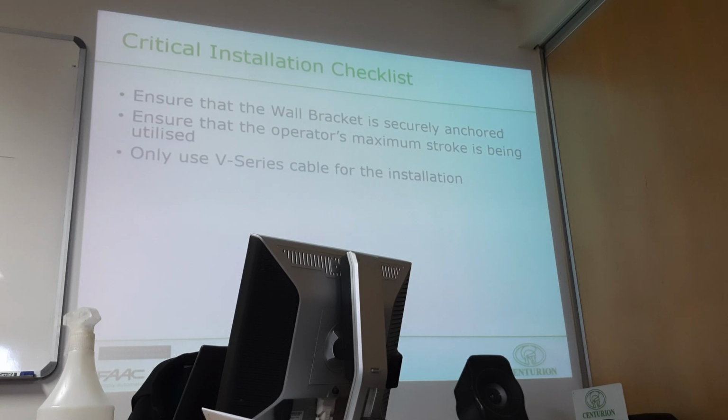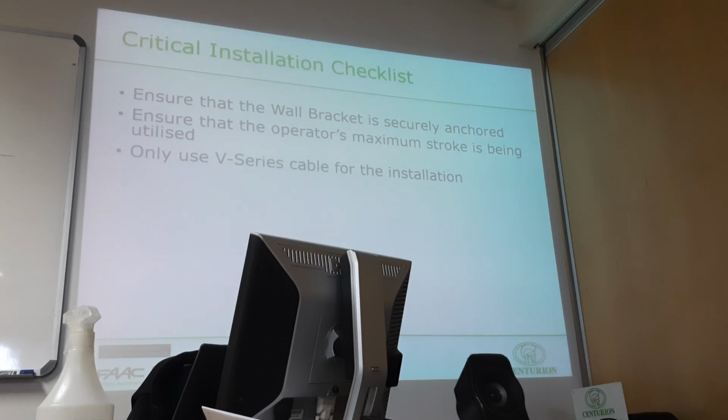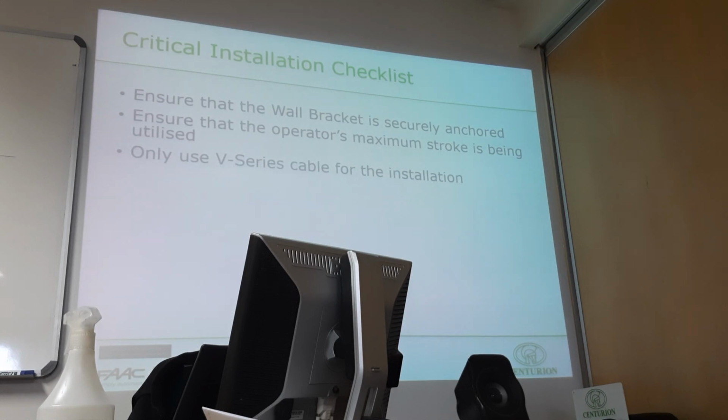Someone takes trailer cable, which is like a Cat 5 but it's got 7 cables in it, which is not shielded. So it's a nice thick cable, but it doesn't protect against any outside interference from the world into this controller. Then you have the DOS issues. Then it doesn't work, it's jerky, it doesn't count, it goes into collision because the cable's not good. So it's important to use the V-series cable.